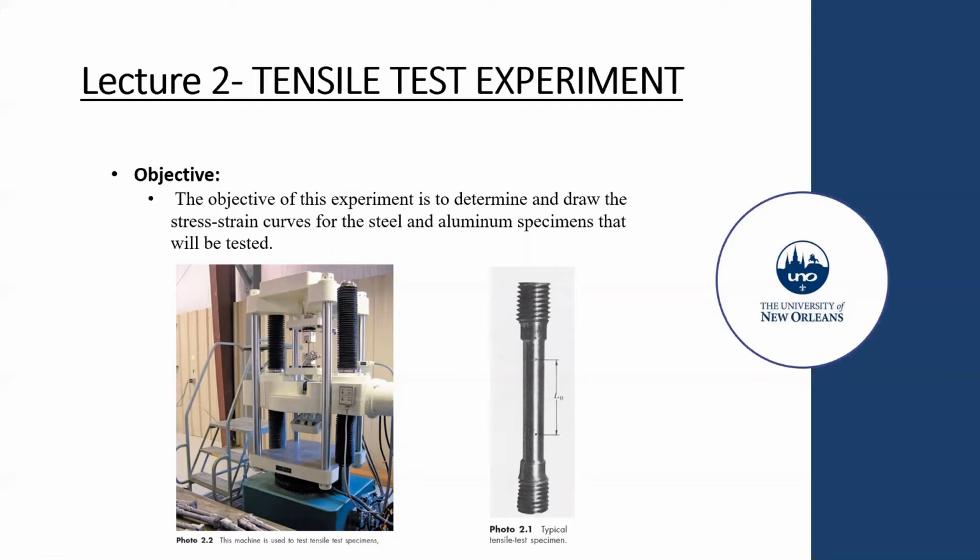Okay. So tensile testing is one of the simplest and most widely used mechanical tests. By measuring the force required to elongate a specimen to breaking point, material properties can be determined that will allow designers and quality managers to predict how materials and products will behave in application. So when you put your design in service after the construction is completed, you want to forecast how it will behave in advance.